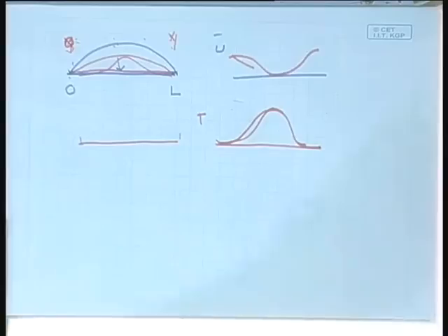So, what you see is that when you have a standing wave, the energy flows in and out like this, and it gets converted from the potential energy, where the energy is mainly concentrated at the nodes, to the kinetic energy, where the energy is mainly in the antinodes, and then it flows back to the nodes. Okay. So, this tells us how the energy flows, how it is distributed, and how it moves around in a rod like this when we have a standing wave.